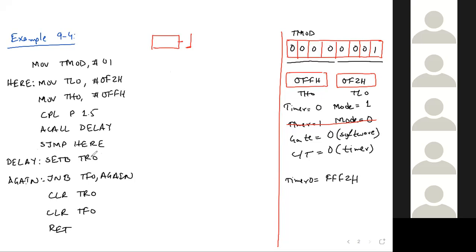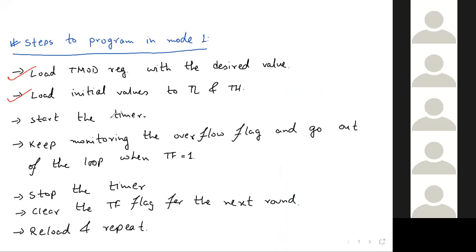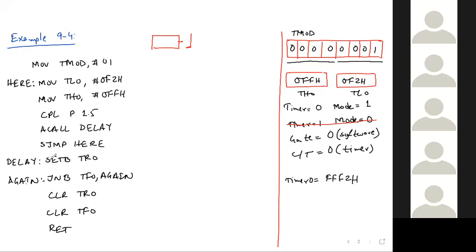Sir, in order to start the timer. Exactly, in order to start the timer, and that is our third step, start the timer. So how do we start the timer? We start the timer with this line, that is SETB TR0.